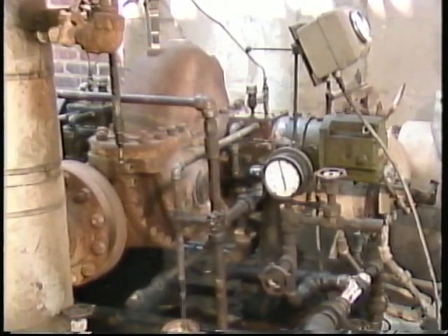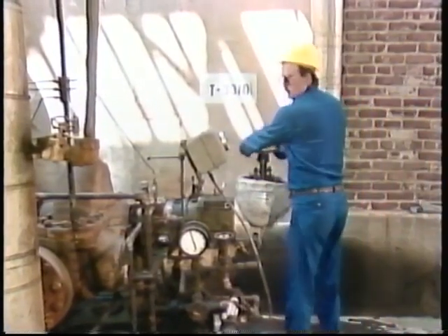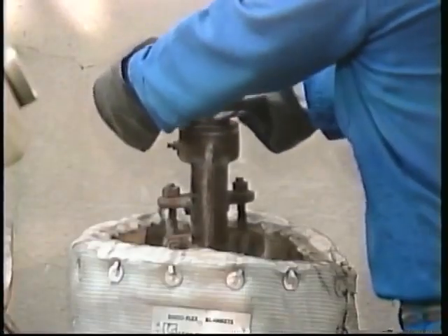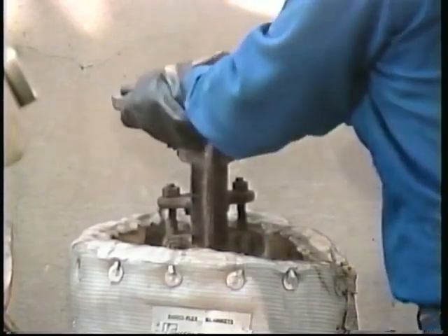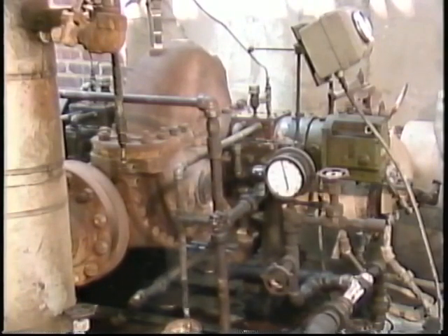After a sufficient warm-up period, which is usually stated in your facility's operating procedures, the turbine startup can begin. First, slowly open the throttle valve to bring the turbine speed up to about 10 to 20% of the normal speed. This part of the startup is often referred to as heat soaking. It allows both the rotating and stationary parts of the turbine to come up to normal operating temperature evenly. Company procedures usually dictate how long the turbine must heat soak before you can continue the startup. After the heat soaking period, the turbine can be brought up to normal operating speed.